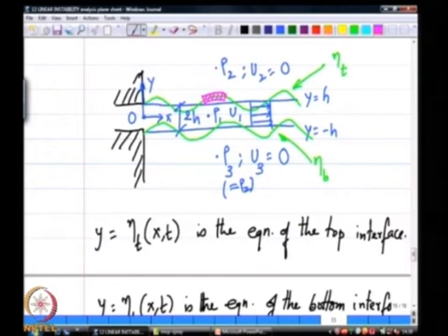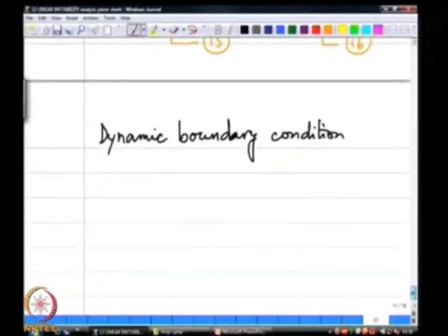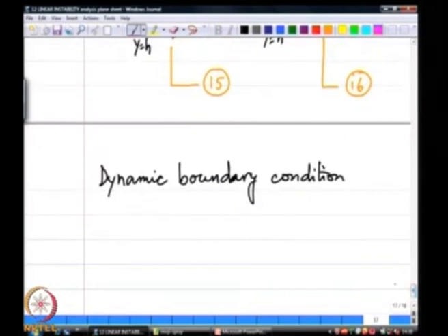and write down the force balance on that element of fluid, that element of fluid is chosen to span both fluids, but of an infinitesimal thickness. So, its own mass is nearly 0, which means the pressures acting on both sides and the net resultant forces should all balance out. If force equals mass times acceleration and the mass of the element is small, then the forces are all equal, it is in static equilibrium. That is what we call the dynamic boundary condition.